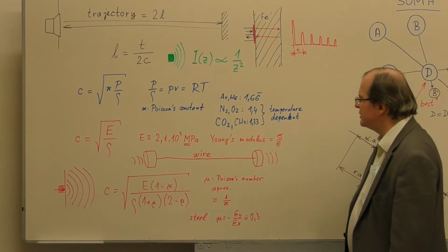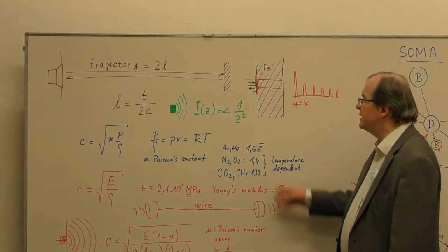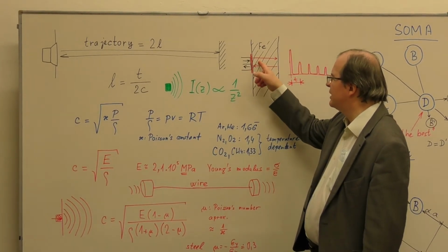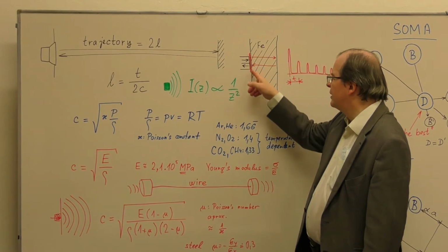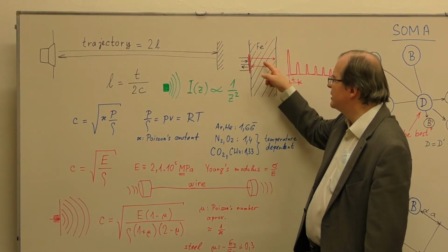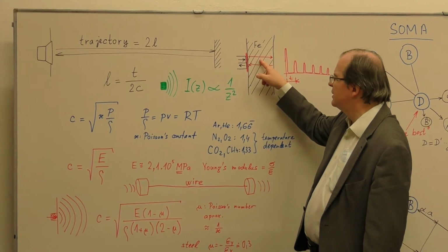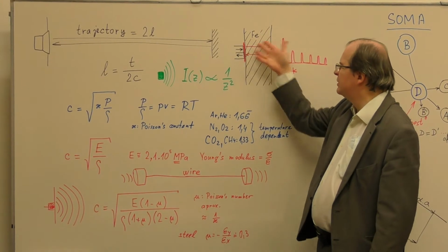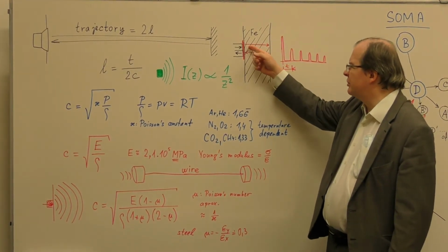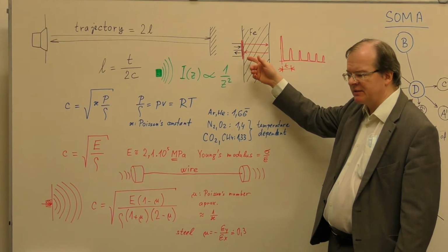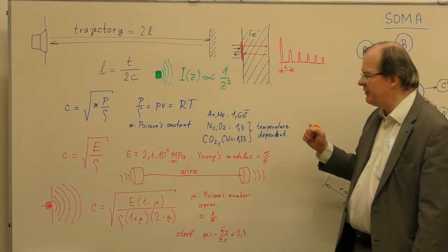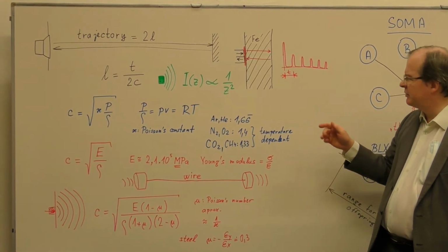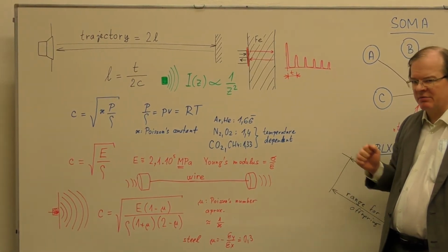For steel, another important thing is that the air between the sensor and the material can't transmit energy into the metal. So here should be some medium which will transfer the sound, a typical white grease. We will try to measure the thickness of steel in our laboratory.